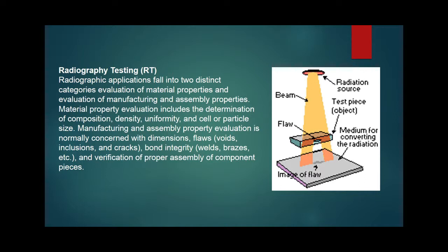Some common uses are detection in surfaces such as welded parts, castings, and forgings, wall thickness measurement, corrosion mapping, detection of blockages inside of sealed equipment, detection of reinforcing materials in concrete slabs, and measuring bulk density of materials.